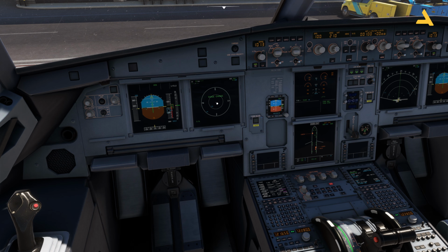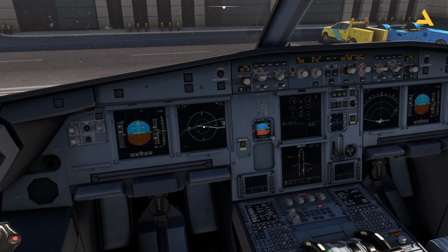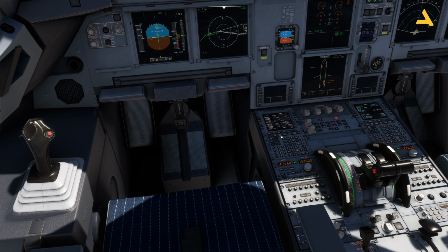Okay. So now this green part is telling me that I have a flight to follow, which is there in the primary flight plan. But this white line is telling me that I will change my flight. So I will just come all the way here. Then at this point, I will just go back like this straight, because I haven't entered anything. And if at any point, if I click activate secondary, the secondary flight plan will actually become my primary flight plan. But I'm not going to do this, and I can always delete it.